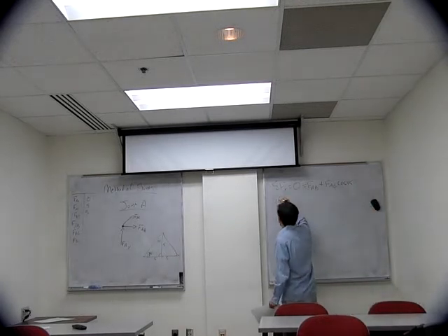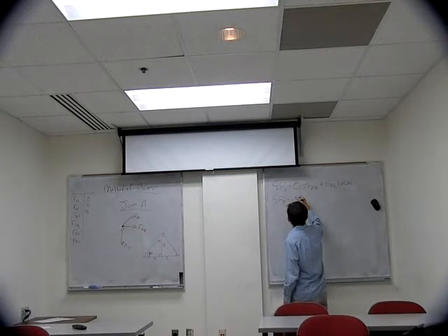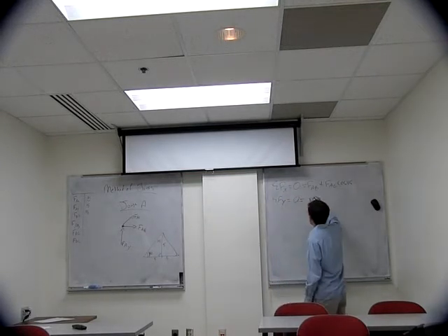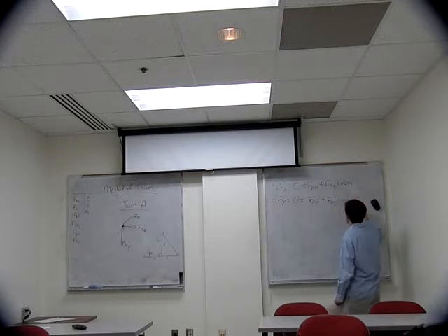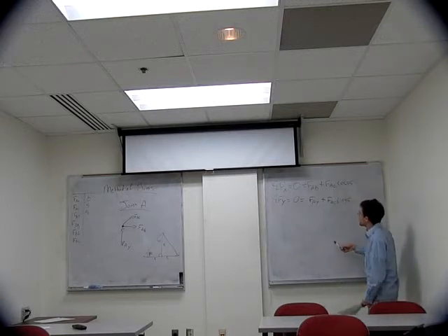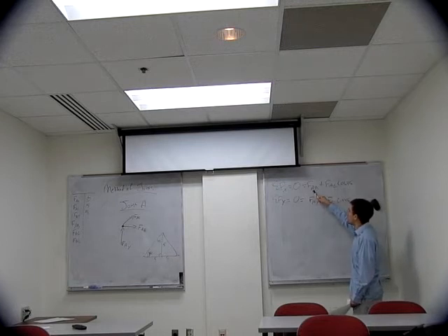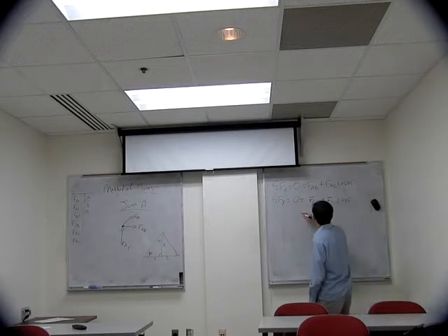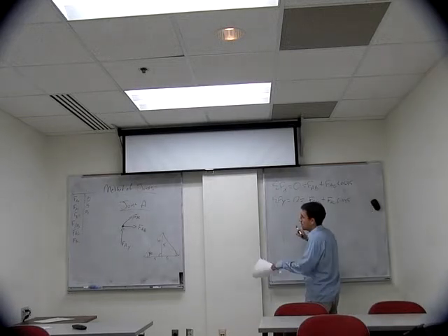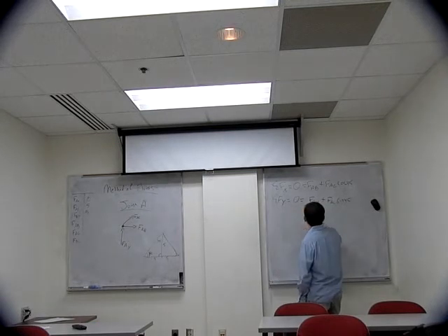If we do the summation of the forces in Y, which we know would be equal to 0, we have our reaction force at A in the Y direction, and we have the Y component of Fac. So if we look at the summation in X, we don't know what Fab is, we don't know what Fac is, so that one's not useful yet. But here, we know Fay, we don't know Fac, but we can use this to solve for Fac. So the member force in member AC.